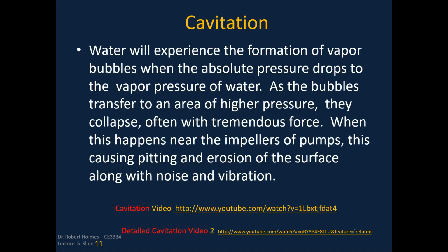So I want to now get onto this concept of net positive suction head, what it is, and it really revolves around the concept of cavitation. Cavitation is defined as when water changes from a fluid to a gas. If you put water on the stove and you boil it, you turn the heat up and it's going to boil. At sea level, that's about 212 degrees Fahrenheit. It's changing from a liquid to a gas, but we're adding temperature to it.